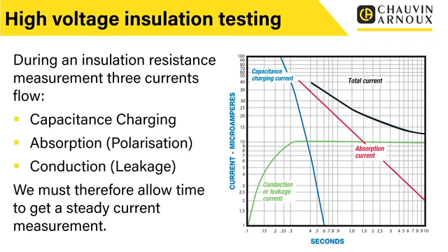So just be aware when we're carrying out these tests, this is why we can't just connect it up and say, right, that's your reading. We do have to leave these for a period of time to get a reliable reading of the actual leakage that we want to know and the actual insulation resistance.